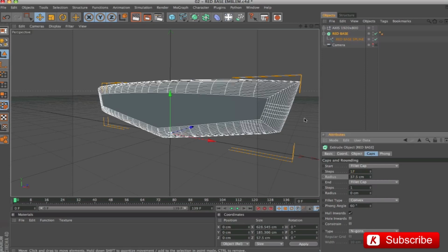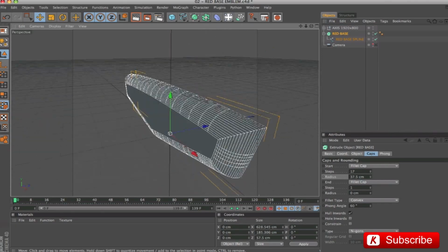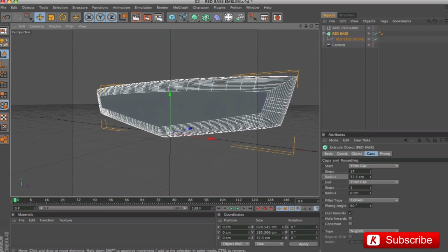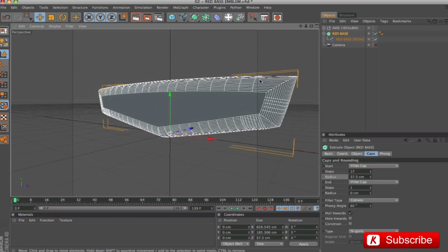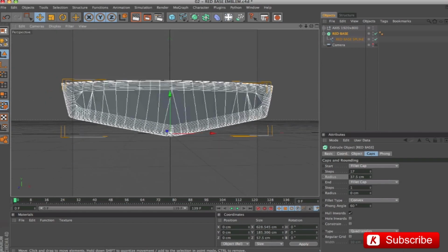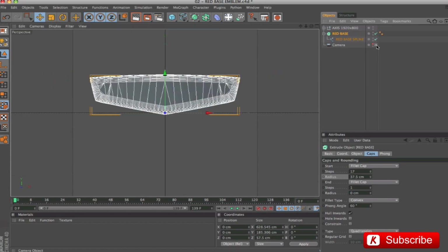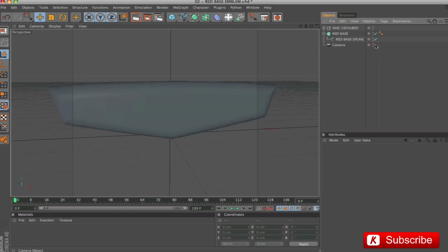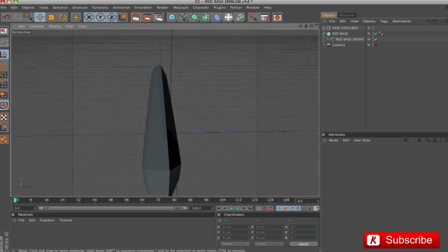Set 17 steps, in convex mode. Finally, in the front extrude, use quadrangles mode. We can see the result immediately by applying the z-scale value 0.3.